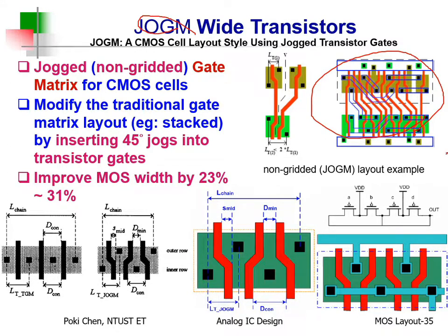With more freedom, it means we can squeeze more performance. We can reduce the layout area even more. You can see the only constraint is 45 degrees jogs. That's it. But according to length, sorry for that.